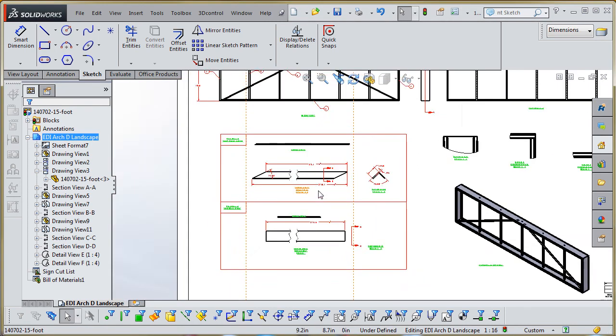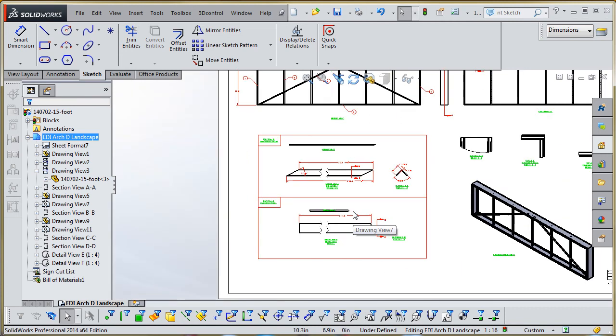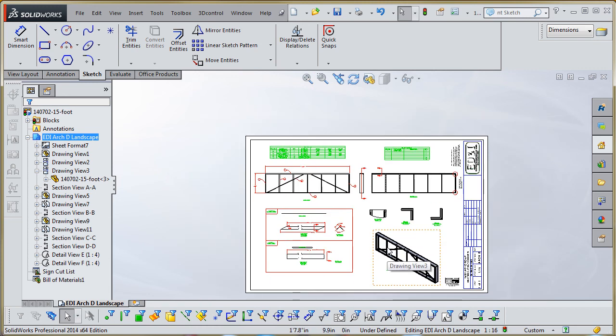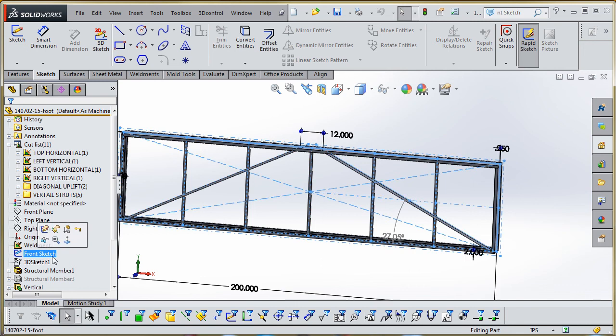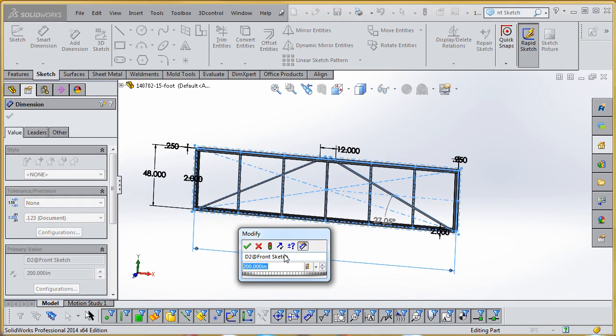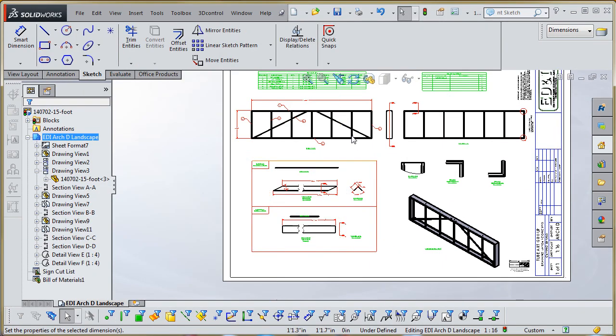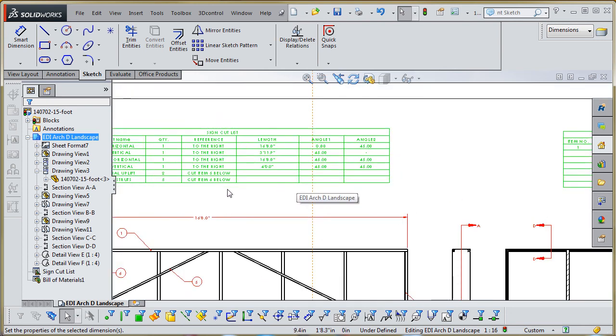But you can see, just to demonstrate how this works, that you can very quickly generate a whole new drawing for a whole new model with different dimensions, and create these shop drawings for your shop relatively quickly. So in summary, what we have here is a drawing format based on a model. The model is based on a simple sketch, the front sketch. With that front sketch, you can make generalized modeling changes to your model. From those modeling changes, you can rebuild your model and get that reflected back in your drawing, so you can generate shop drawings down there for your shop guys.